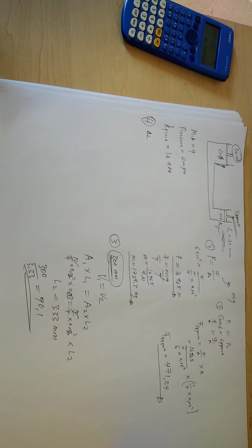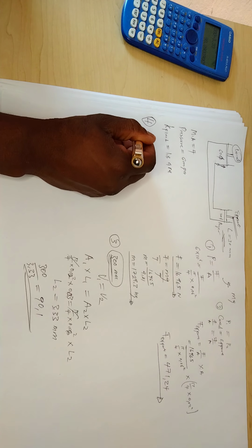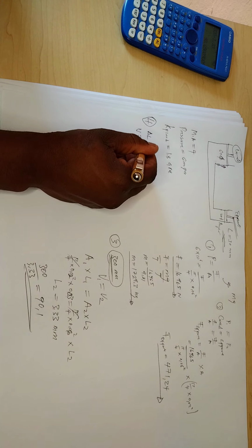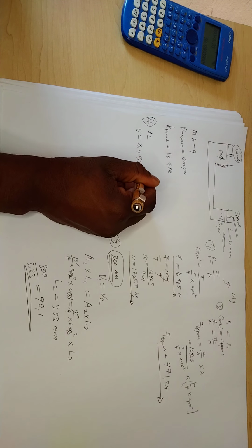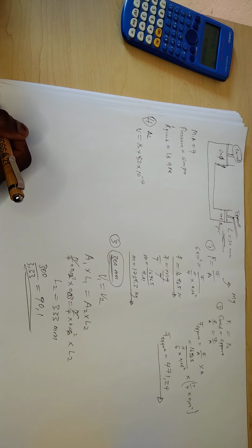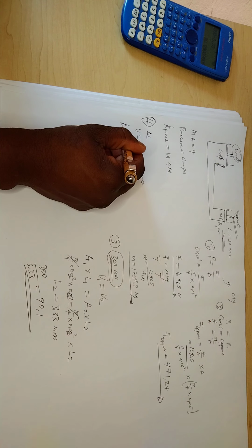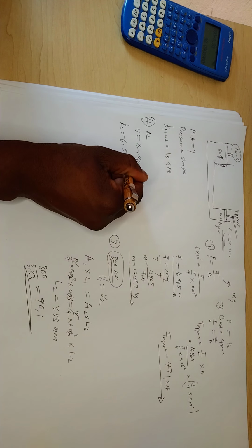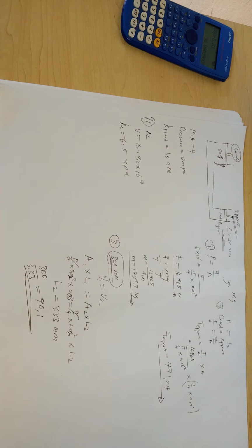Calculate free play on a RAM if the volume of fluid is, so they give us a volume of a fluid, 8.482 times 10 to the power minus 4 meter cubed. They say take the bulk modulus of the cylinder. So they give us K cylinder as what? 6.5 GPa. This is what they gave us. And yes, so they want us to calculate that.